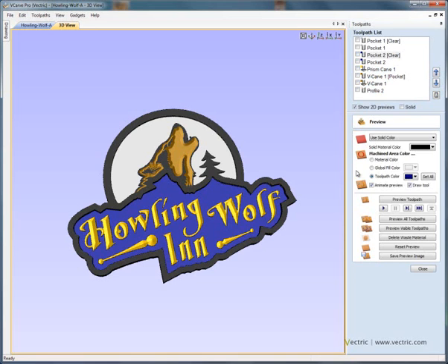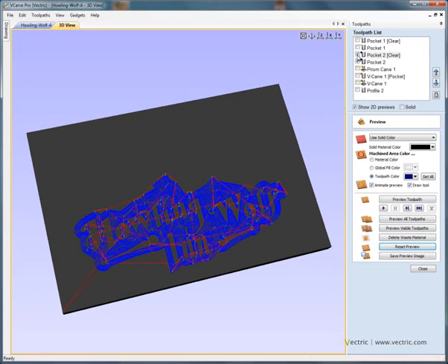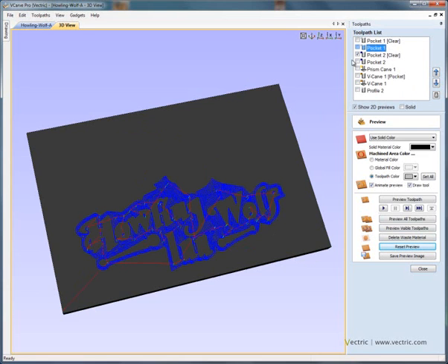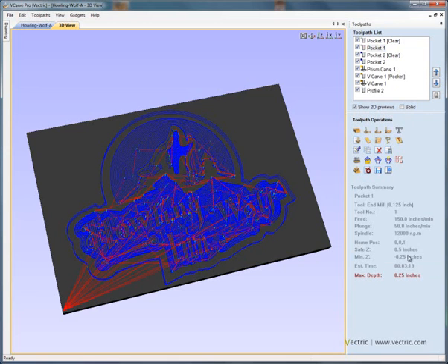If we just reset the toolpath for a moment, so we say reset the preview, there we've got our 36 by 24 panel, and we can see that we've got lots of different toolpaths here making up the project, and that they may be too big to cut on our CNC machine. If we want to draw all of the toolpaths, we can click on a toolpath, right mouse click and say show all, so this draws all of the toolpaths in the 3D window for us. Let's close the preview menu for a moment.